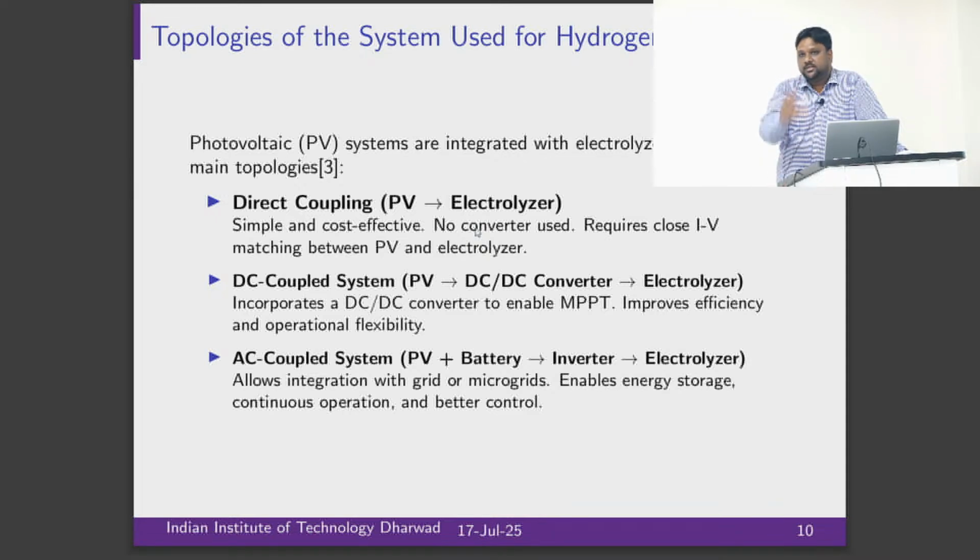If you remember yesterday, we were trying to control a DC-DC converter. Of course, it was for the electrolyzer, but I showed you how to control the output voltage of a DC-DC converter, right? The same DC-DC converter, the reference you are giving, you remember that reference, whatever application I told, that reference you can set to the voltage corresponding to the MPPT point. So any time you change your system condition, it will try to track that reference voltage.